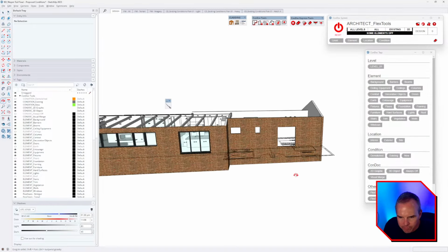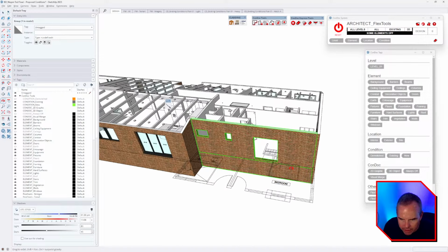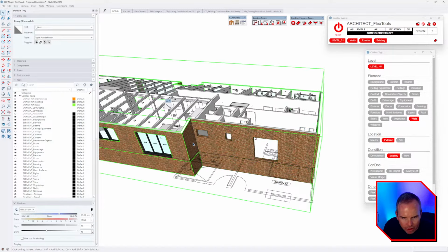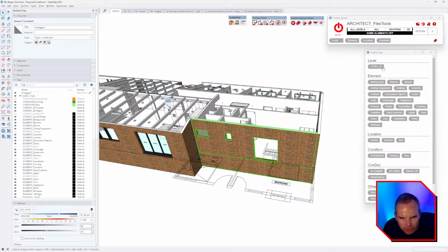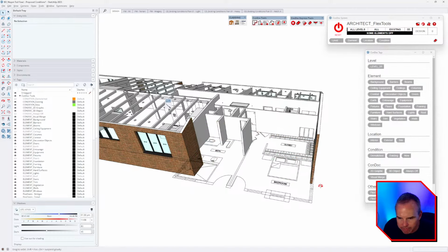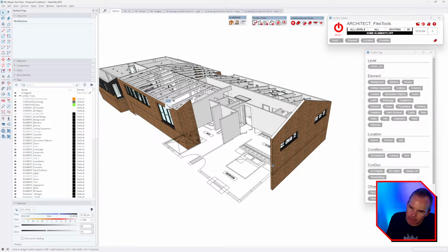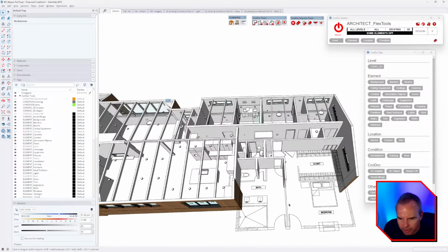Okay. All right, so now this wall right here, these are level 1 walls exterior existing. Well, this is going to be level 1 walls exterior demolished, like that. So now when we create our demolition plan, that'll automatically show up as a dashed line, which will indicate that we're getting rid of it.